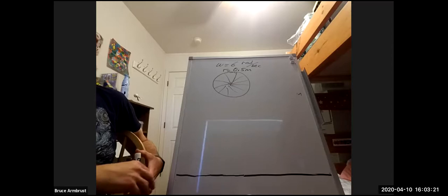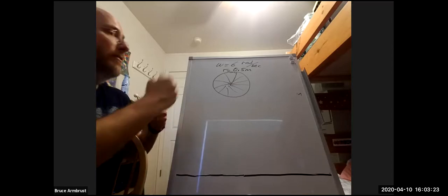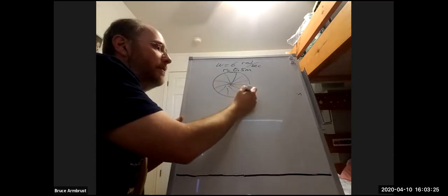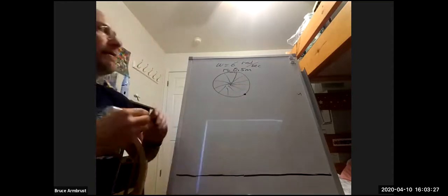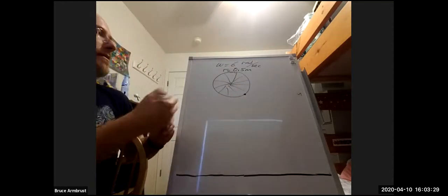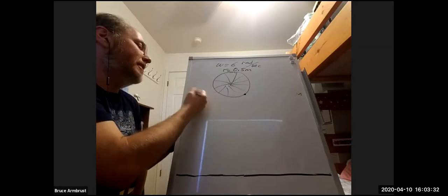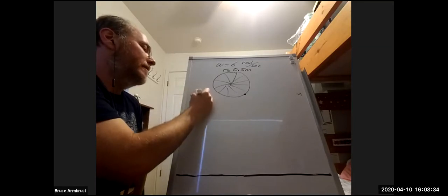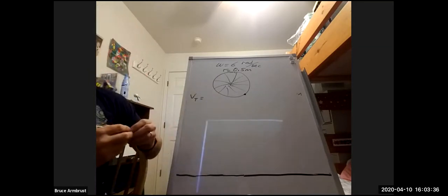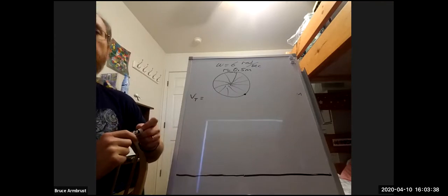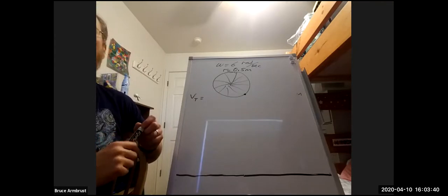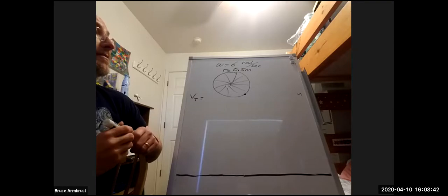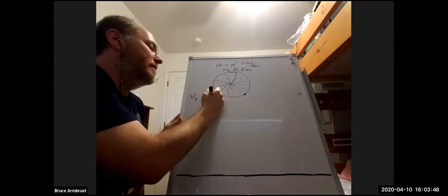All right, so let's just think about what we know about this. If we're out on the end, let's think about a point that's out here. Let's calculate some things. First, let's get its tangential velocity. How fast is that thing moving tangentially? It would be 0.5 times 6, right? Yep, it's just r times omega.